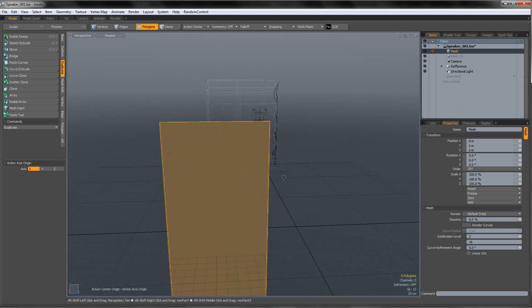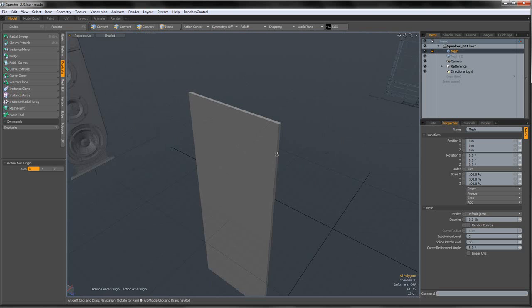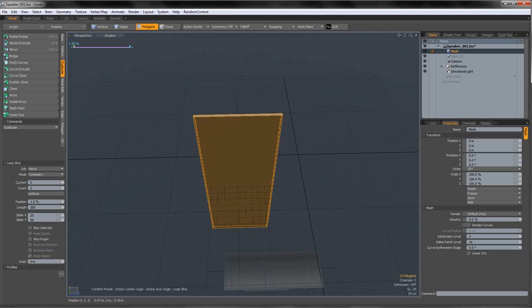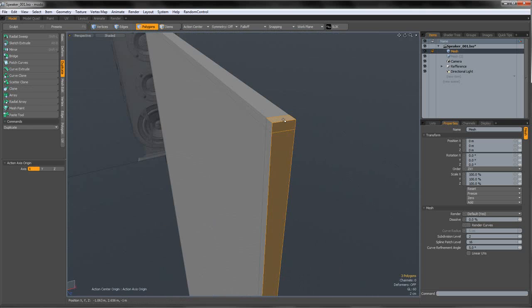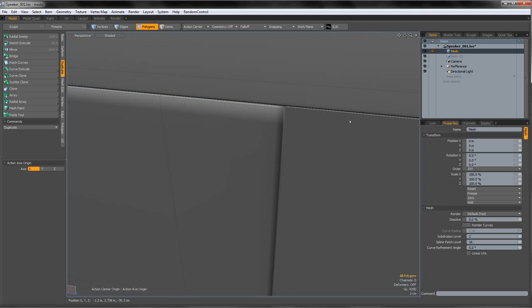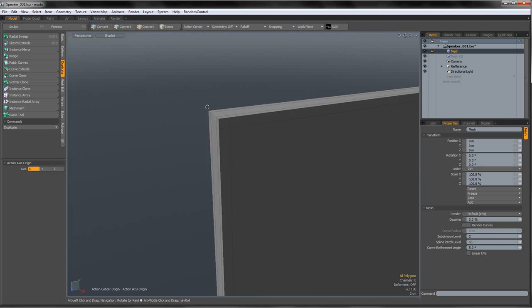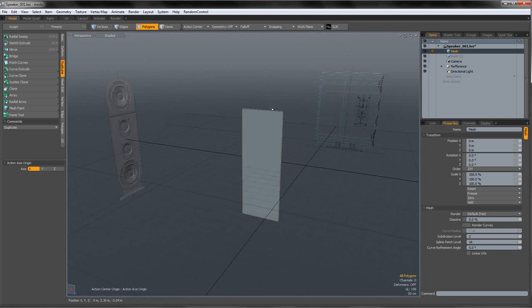And now we're going to repeat the process for this bit. Okay, this is basically a cube, so we're going to change the mode to symmetry and the count to 2. And we're going to add them in. Okay, and we're getting those very, very smooth corners because we have a very big distance to smooth.